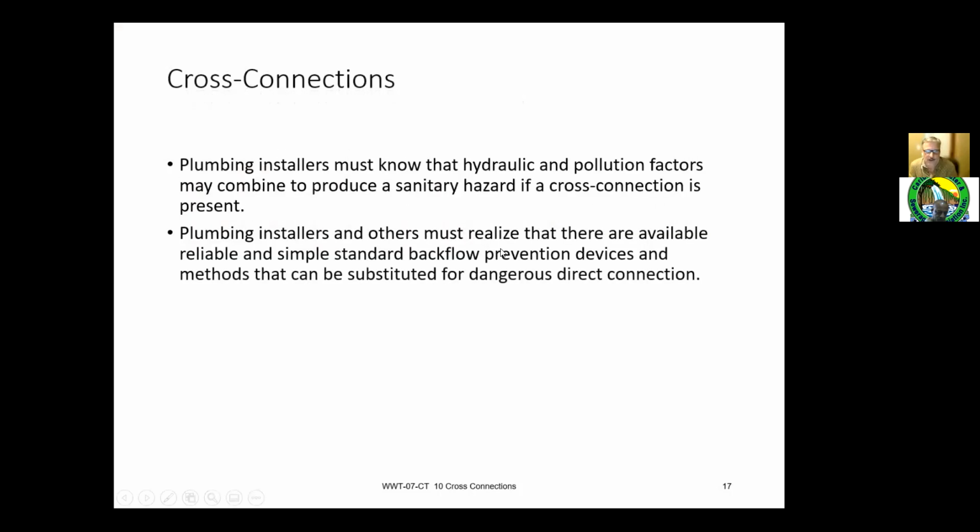So plumbing installers must know about hydraulic and pollution factors. They need to be aware of cross connections when you call a plumber in to connect the lines. If they're not made aware, they would do exactly what I just said. They connect to the closest water line, potentially causing a cross connection.